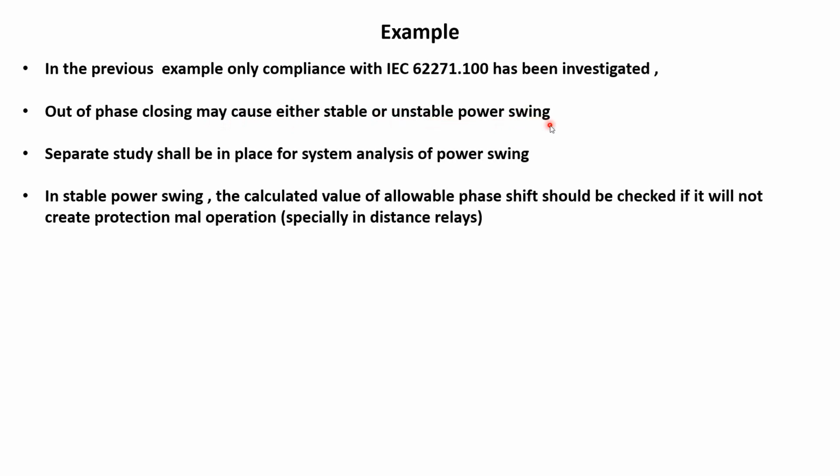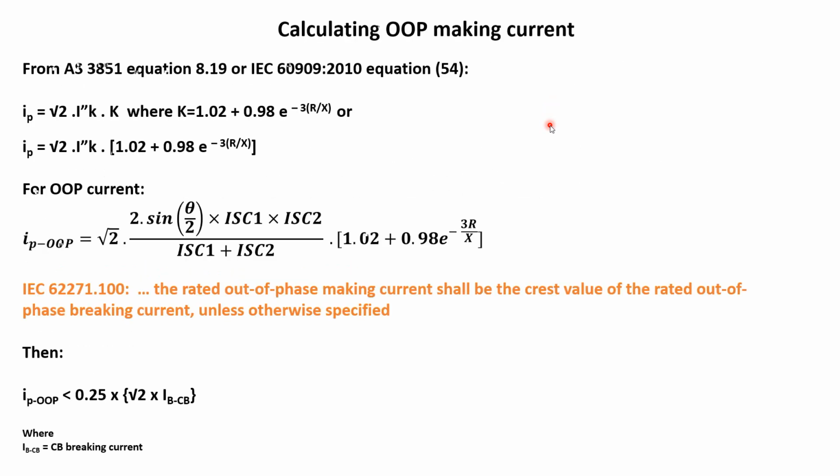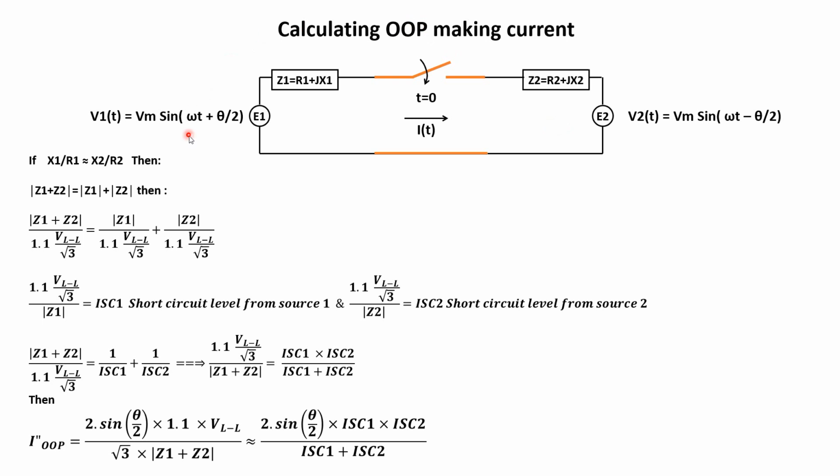So we're expecting to have some sort of power swing, because if this one is positive from this one, the angles, definitely the current is initially going this way, the power. But it doesn't mean that at the steady state final condition, the power of this side is more than the power of this side. In a steady state condition, the power would be from this side to this side. So definitely we have a power swing.